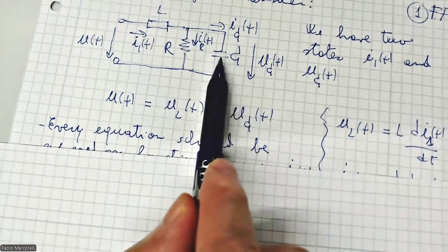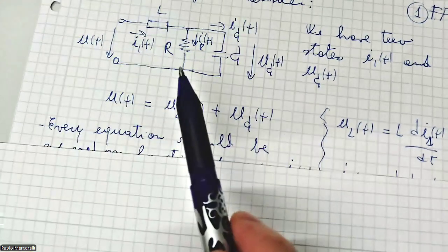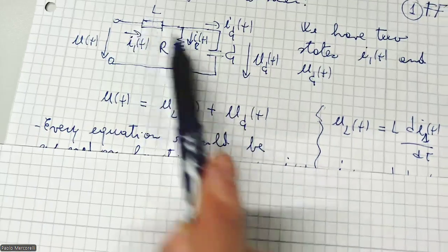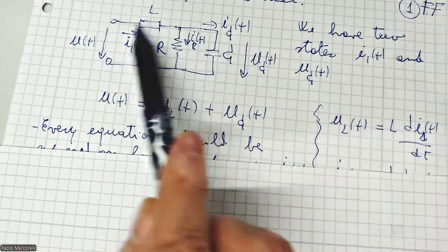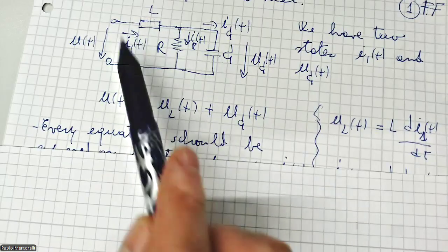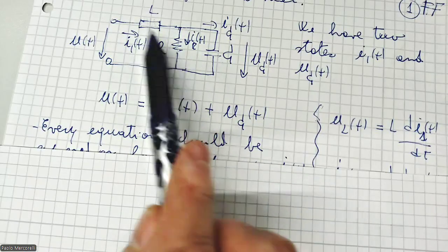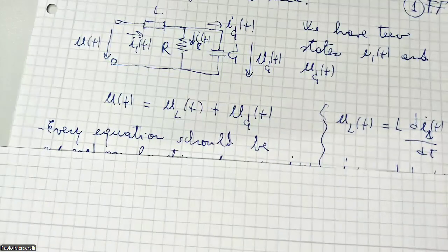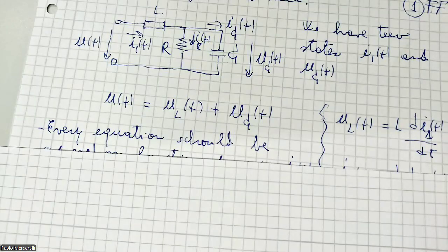In this case, no doubts, because we don't have a parallelism. We have just an inductor and a capacitor. This means the two energies are independent. Independent, as I told you. If you think about a series LRC, it is not the case. So in this case, even though they have the same current, we have two independent energies, because the nature of this energy is basically different.